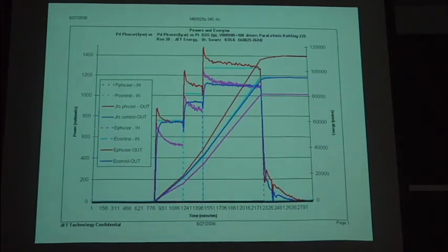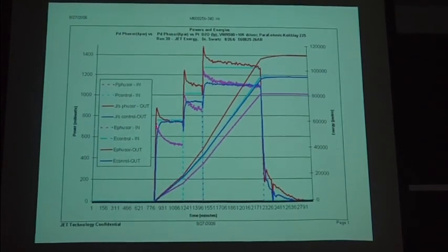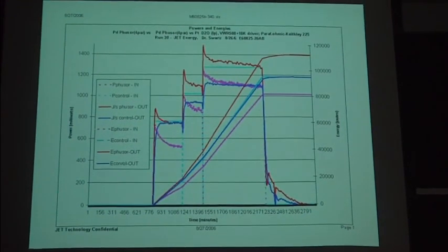These curves are the power, they're read off on the left. This is between 0 and about 2,000 minutes. Here's our input to the ohmic control. Here's the output. You notice we can almost capture all of the heat. This is because we're having the heat go to the Stirling engine. We're not going to capture it all. In the other systems, we could, because it was relatively insulated. Here, we're letting the heat escape to go to the motor, and that's why we're not quite coming up to it. And here, we're not coming up to it at all.